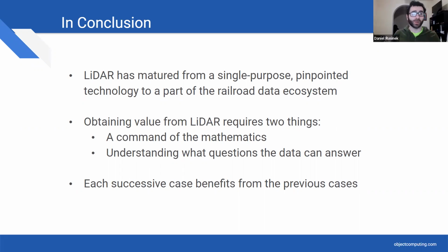And just to add on to what Marty said, it also depends on what use case you're looking for. In this case, if you're looking for vegetation, basically, if you take multiple scans in the same location, you can subtract them from each other and get an estimation of, for example, how much vegetation has grown between scans. But in areas, for example, in the northern United States, or in colder areas in the winter, you're not going to have a whole lot of vegetation growth. So that's just something to take into account. Whereas in the south, you're going to have vegetation growth pretty much all year round. So that's another consideration.